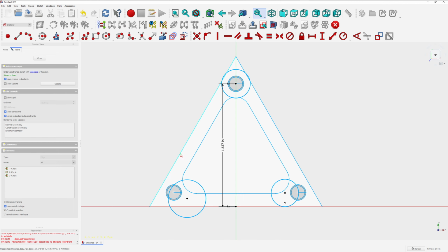And now we need to bring the geometry from the previous sketch through. Just before we continue, I forgot, let's put the dimension of 0.374 on the circle. Select the first circle, shift click, and then equals. Okay, now select the circle and the line and tangent. And then select this one, tangent. And then select this one, tangent.